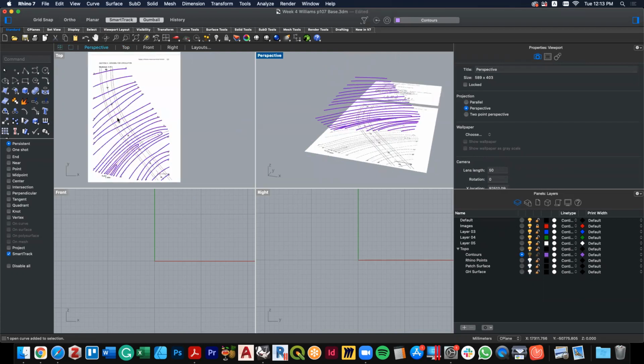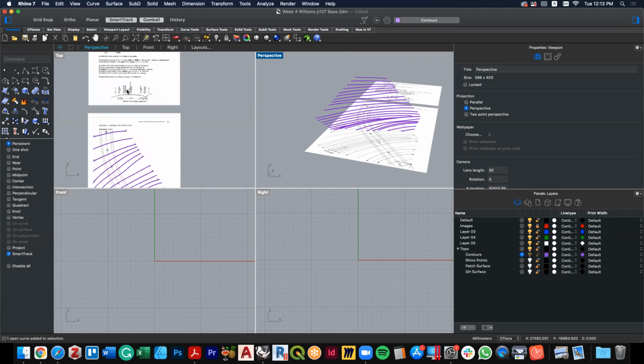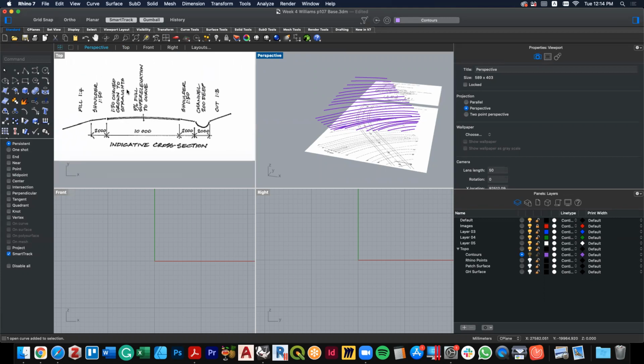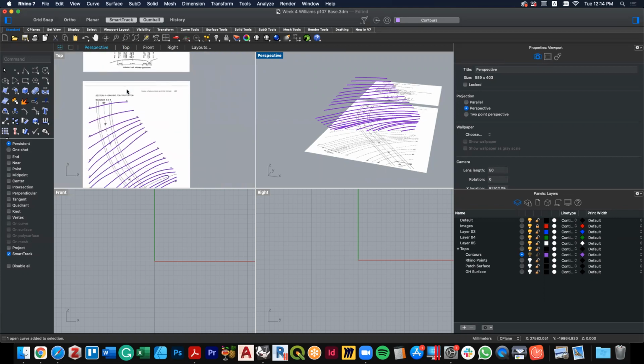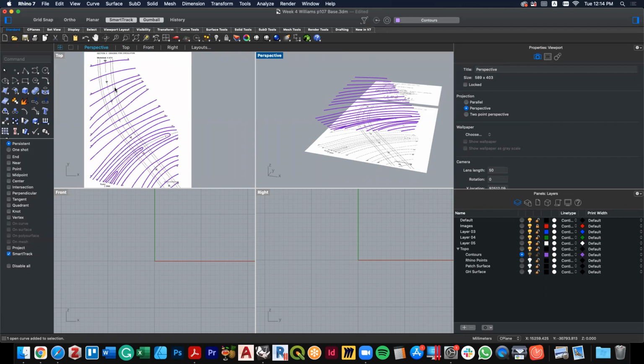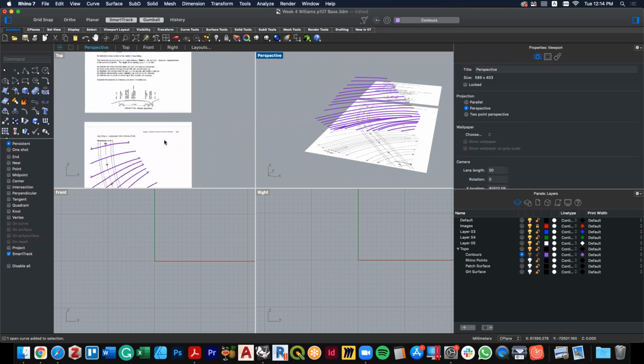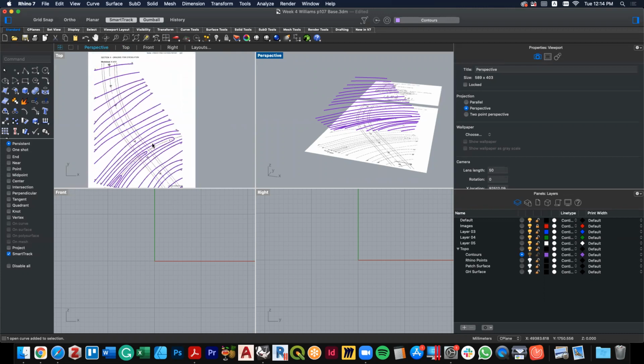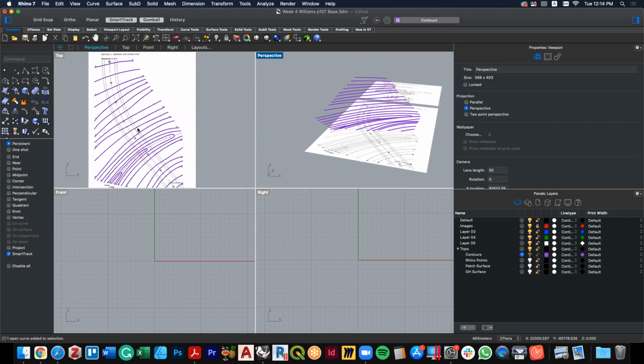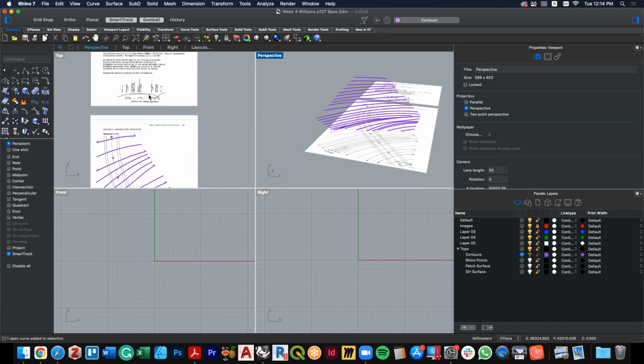So I'm going to do this exercise in Grasshopper, and I'm not going to do it exactly. I'm not going to work with the super elevations that Williams specifies. I'm going to treat it like there's a uniform curve all the way along. Basically the operation is that I'm creating this profile in Grasshopper, and then I'm going to sweep it along this path. I'm going to use that center line as the rail curve, and then use this as the swept profile.